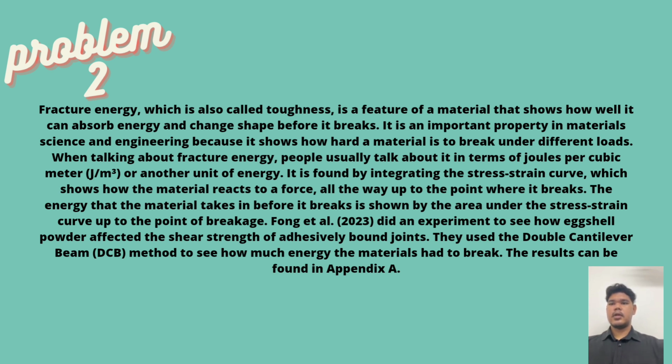It is found by integrating the stress-strain curve, which shows how the material reacts to a force, all the way up to the point where it breaks. The energy that the material takes in before it breaks is shown by the area under the stress-strain curve up to the point of breakage.